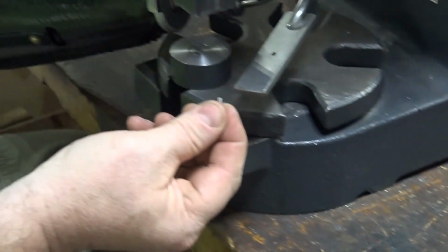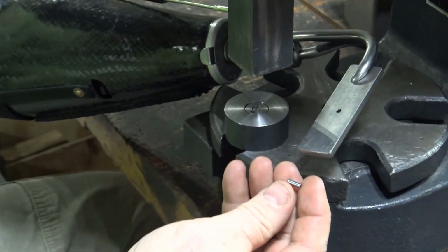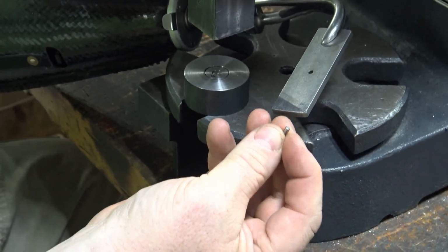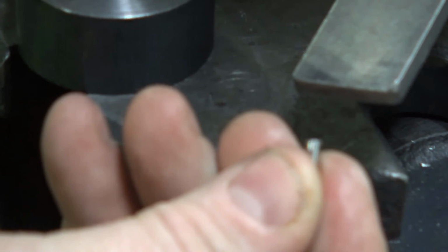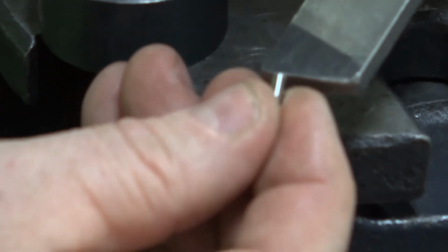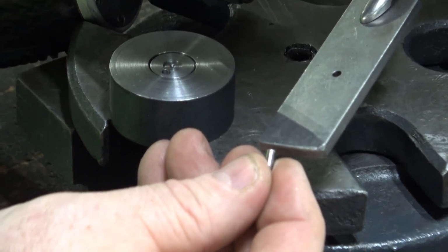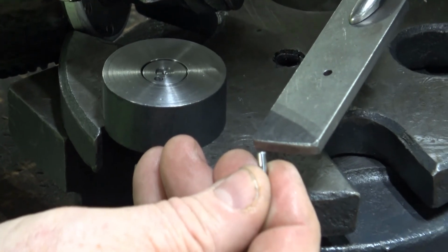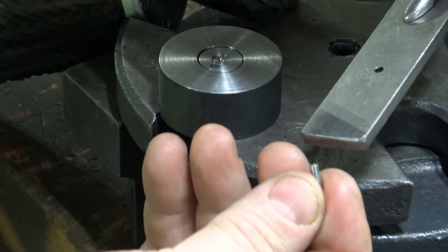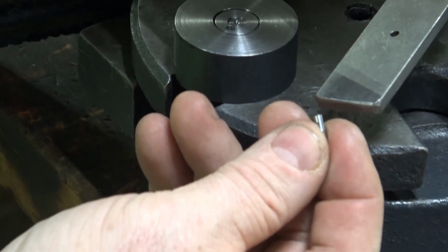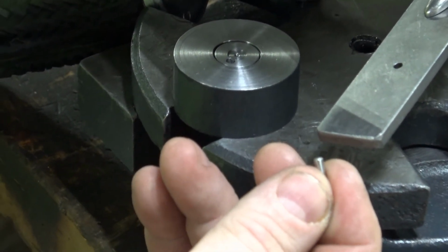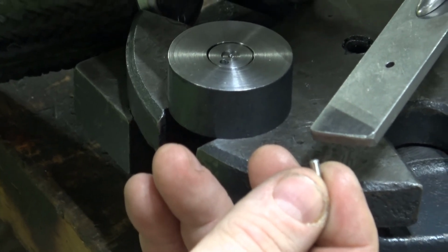So I'm going to pick up one of my dowel pins, and all they are is 1/8 inch diameter, 3/8 of an inch long. It's got a rounded end on it, and then it's got a tiny little chamfered end, and that chamfered end, depending on who you buy it from, can be extremely short. Now because there's an interference fit between the hole that we reamed and this pin, I want this pin to go in really nice. I want it to go in without shaving a bunch of material, because if it shaves material, it's going to ruin or void the press fit that I'm shooting for.